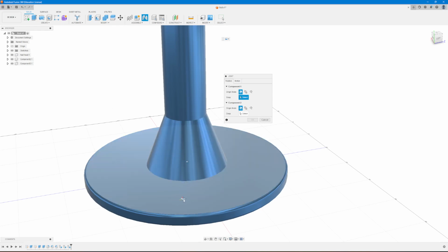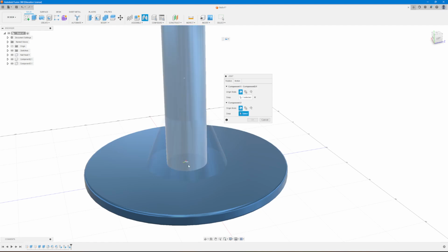This is the object I want to snap to, but it's in the center, and sometimes stuff is in the way. So you hold down Control, and it's going to snap automatically to the center or wherever the object is. If there are multiple things to snap to, it will snap to them as you get to them. But if you hold down Control, it'll snap to that object, and that's exactly where I want it to go. So I'm going to click.